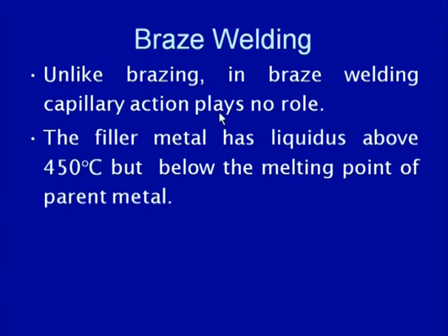So, here in braze welding the capillary action does not play any role in the success of the development of the joint. The filler materials which are normally used for braze welding have a liquidus temperature above 450 degree centigrade, but below the melting point of the parent material. So, this is the normal temperature range for the melting of the filler materials, where liquidus is above 450 and the upper temperature is below the melting point of the parent material.